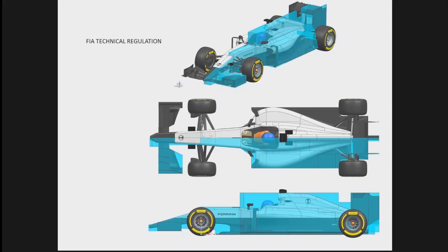I mean, you can do CFD effectively like we did here, which is not transient in the sense that it's called RANS. So it's an average method. It doesn't know about the particles moving with time. It sort of finds a stable state of the flow around the car just through iterations. But we can also do CFD transient called DES, D-E-S.